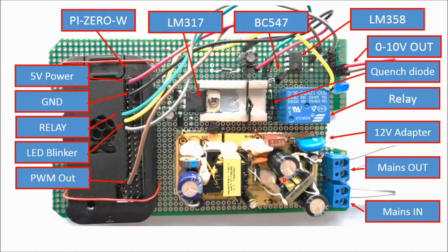This here is the 12 volt adapter. I took the PCB out of the casing and added it on the system PCB as a component. I actually do not recommend you to do so, because if you make any mistake, the mains voltage will be connected to your light fixture and you are liable as you opened the adapter's casing. For instance, if these GPIO wires flip over this side, you have a very dangerous situation. Anyway, you are working with high voltages and people do die from electric shocks, so please be careful.